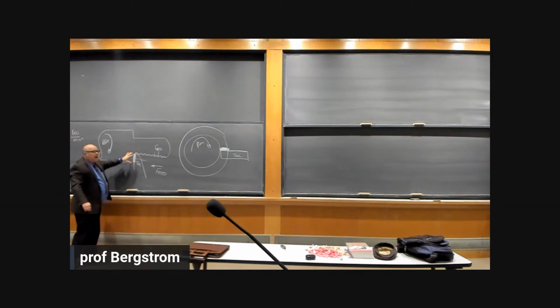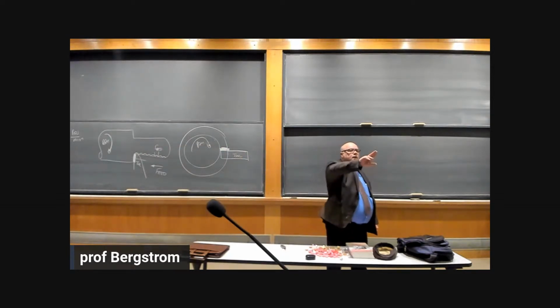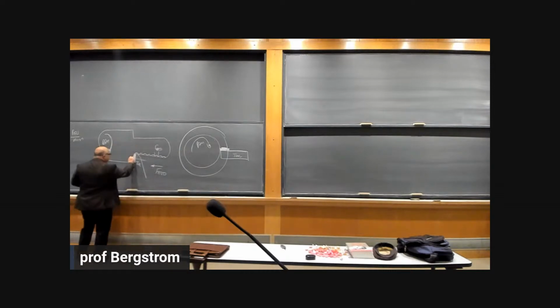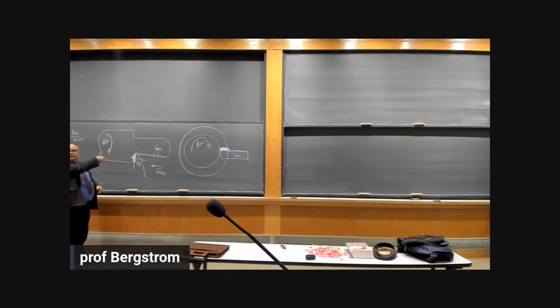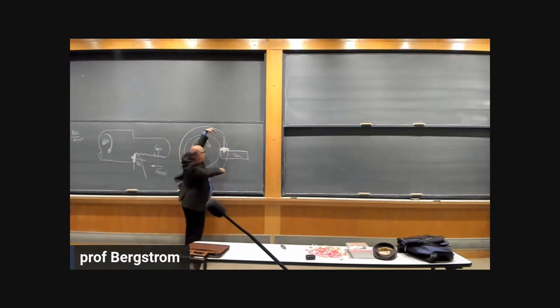Now, when the cutting happens, what we really care about is the surface speed, correct? And what are the units for surface speed? Feet per minute. In this drawing, that surface speed is in and out of the board. It's that direction. It's the vector of how fast this diameter is going past the cutting edge.